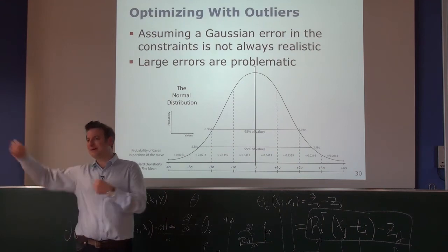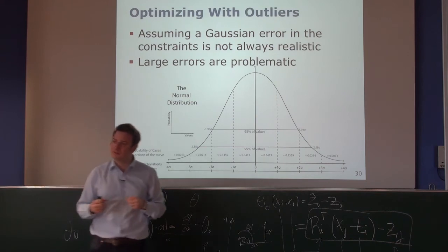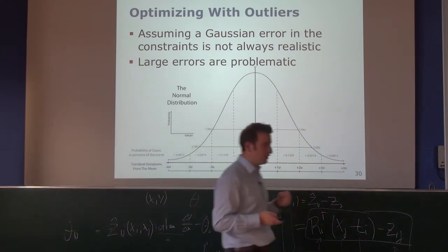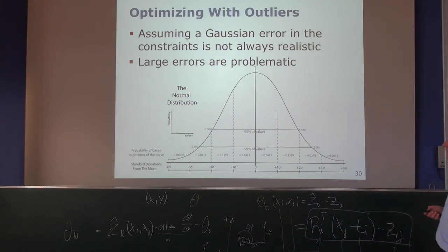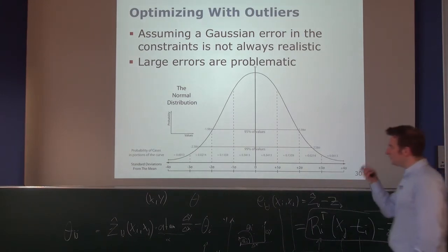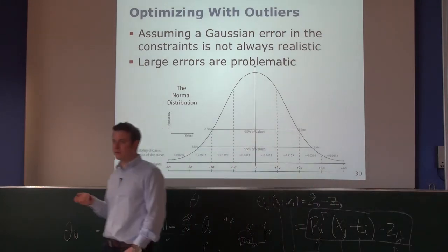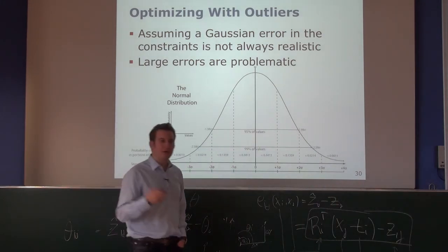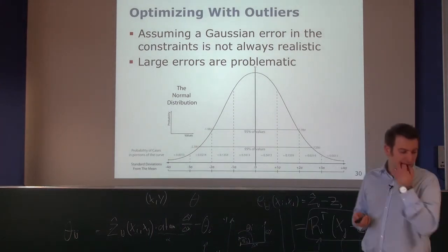And therefore, if you have one outlier which is really far away from the current estimate, the whole mode is dragged in this direction. That's the problem that we have with this Gaussian distribution. And therefore, especially terms with large errors, so if you have constraints which introduce large errors, these are these outliers, this can actually screw up the optimization when computing the minimal error configuration.